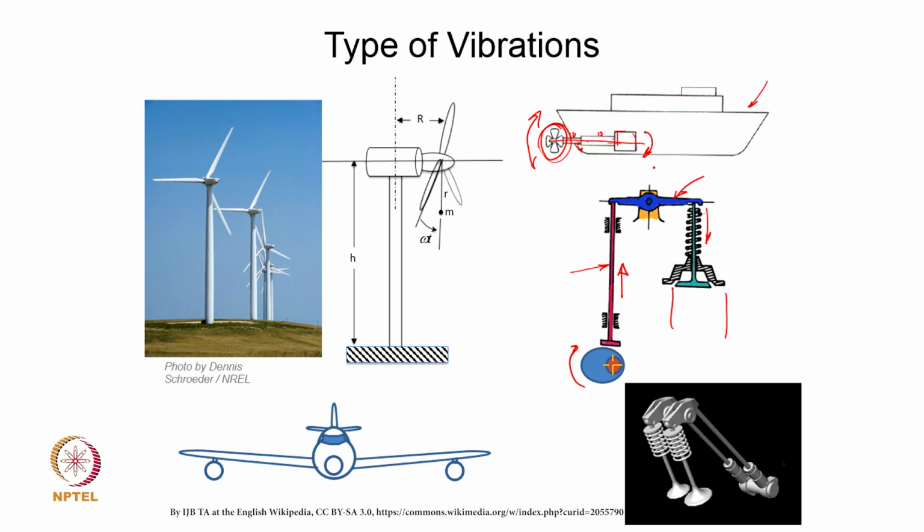and we can expect this push rod to vibrate in the longitudinal direction. So, apart from the vibratory system itself made of the rocker arm, the spring and the valve, the push rod itself can be a potential candidate for longitudinal vibrations. Depending upon the speed of operation of this cam, if it operates close to the natural frequency of the push rod, we can get in trouble here. Okay. In addition, it will be interesting to know the natural frequency of the spring, so that a phenomenon called spring surge does not take place, that is, resonance in the springs is not set up. So, all of these would need you to analyze this system for different kinds of vibration.